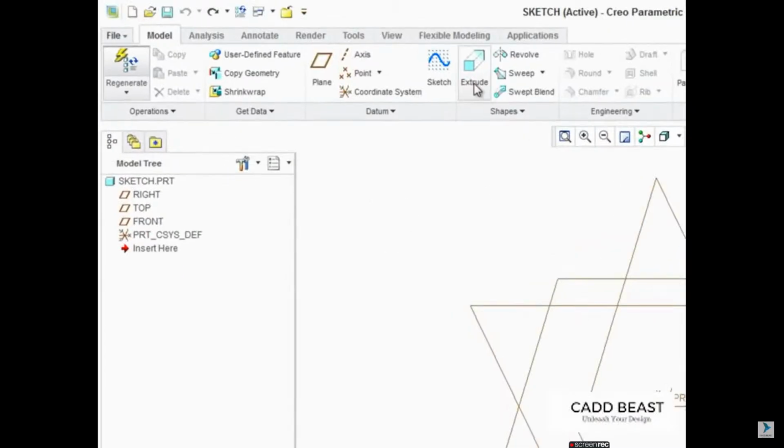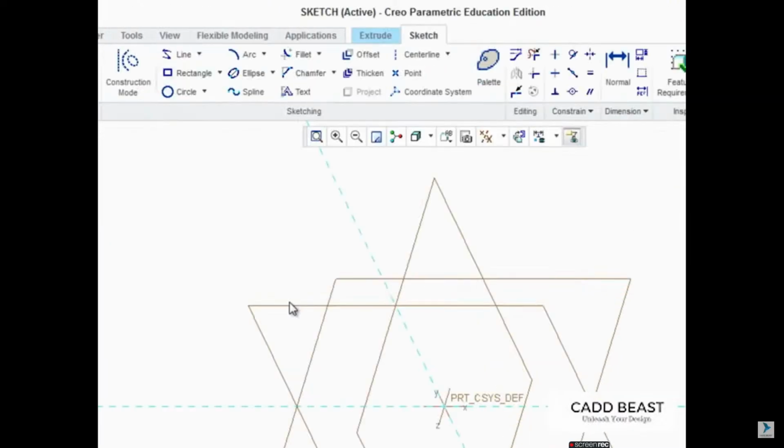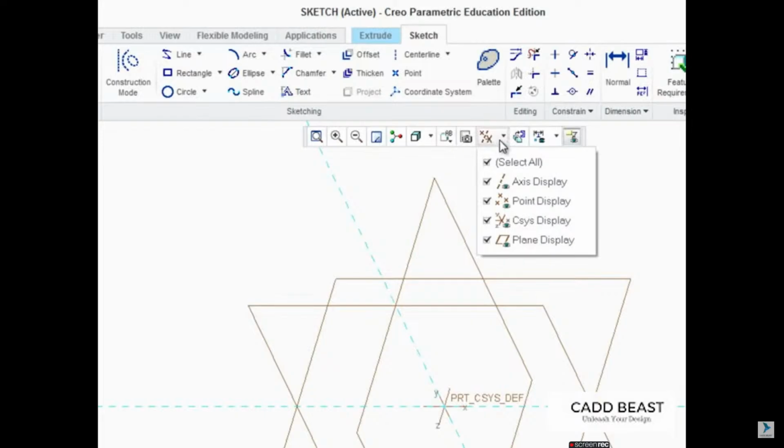Tool and select the sketch plane. That's it. 2 clicks and you're ready to start sketching. Notice that the Sketcher tab has opened, containing all the Sketcher tools required to complete a sketch, and that Creo Parametric starts the sketch in a 3D orientation.